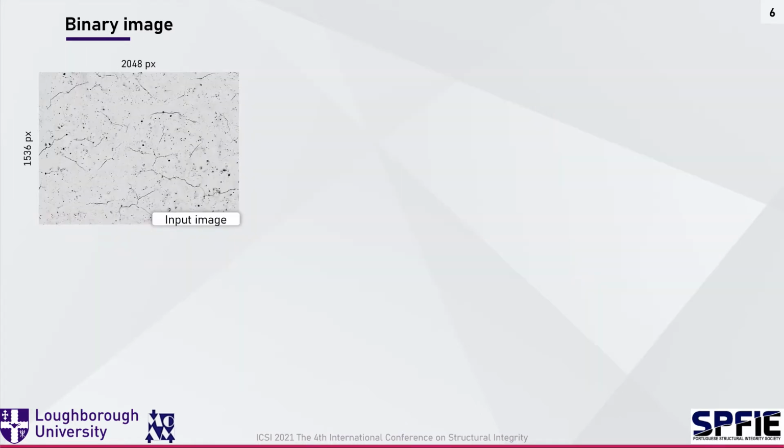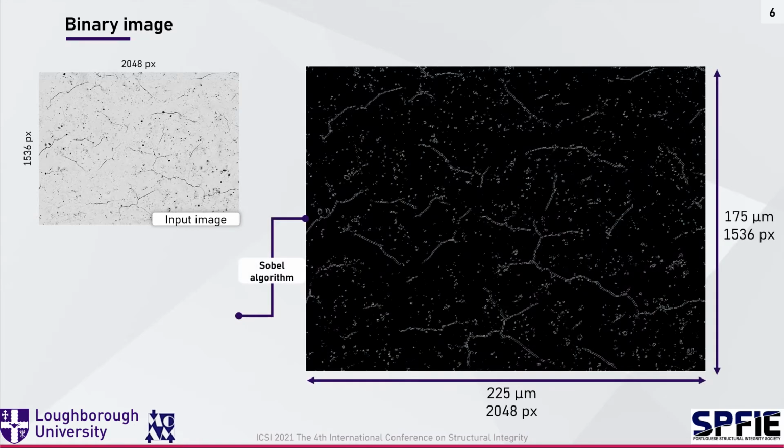After importing the SEM images into the workspace, the image is converted to a binary image using binarization. Once converted, the image is represented as a logical array of zeros and ones. This makes the image quantifiably simpler, allowing calculations and operations to be performed faster.